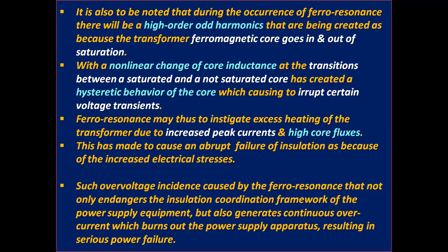Ferroresonance may thus instigate excess heating of the transformer due to increased peak currents and high core fluxes. This can cause an abrupt failure of insulation because of the increased electrical stresses. Such overvoltage incidents caused by ferroresonance not only endanger the insulation coordination framework of the power supply equipment, but also generate continuous overcurrent which burns out the power supply apparatus, resulting in serious power failure.